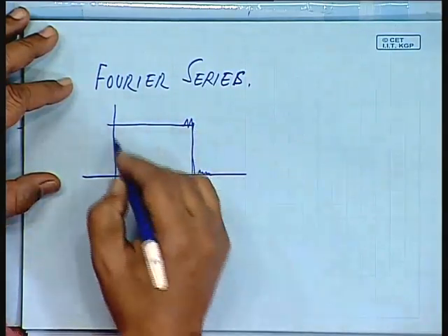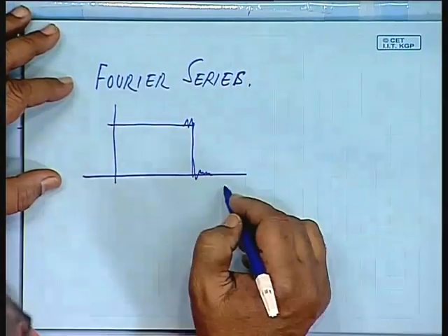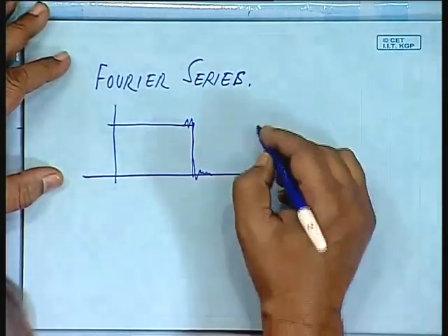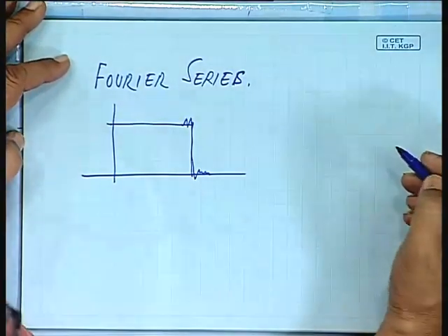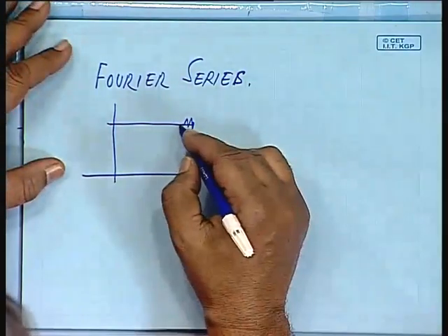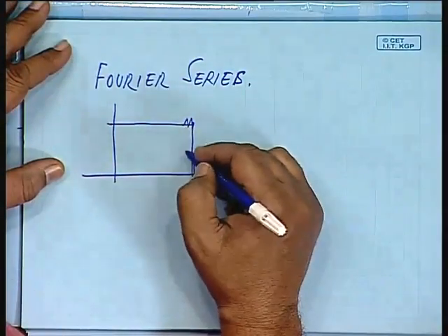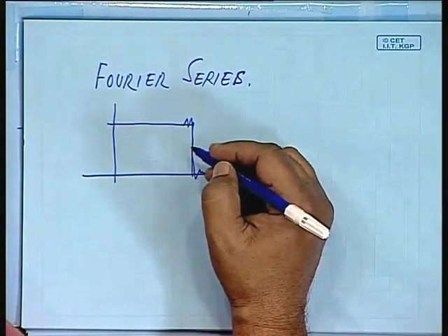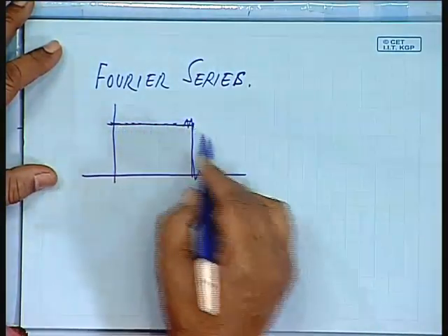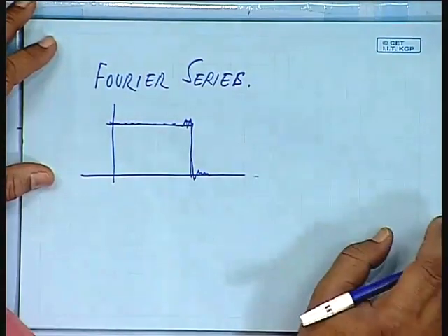ripples. So, we wanted to reduce these ripples, that is, the transition should be smooth as far as possible. So, we went for those window functions other than the rectangular window. But mind you, with those windows you may have a little bit of reduction in the ripples, but the error will be more. Error is minimum with the actual Fourier coefficients wherever you truncate. So, we did not have any control over the distribution of the error in this entire span. We did not have any control.